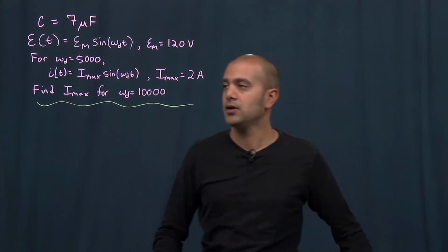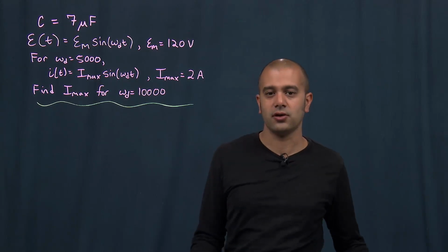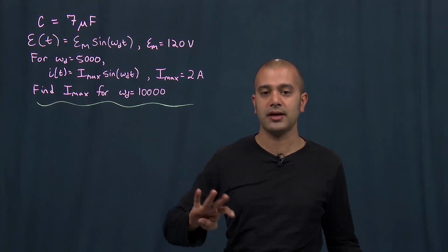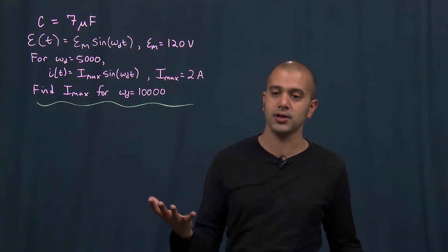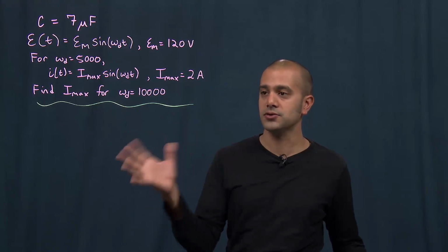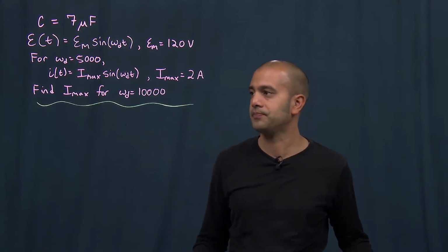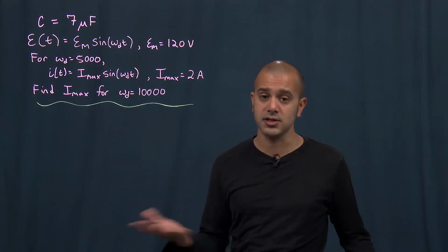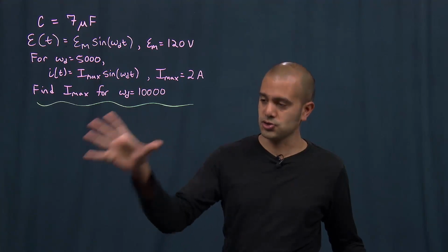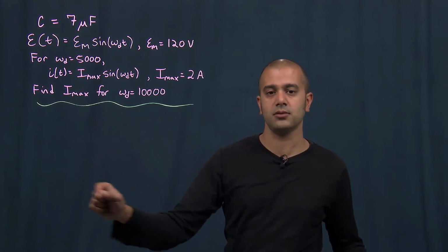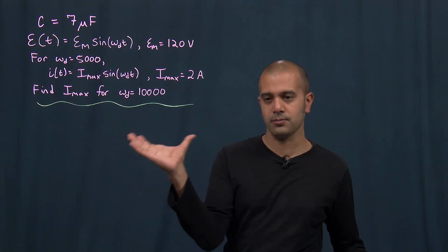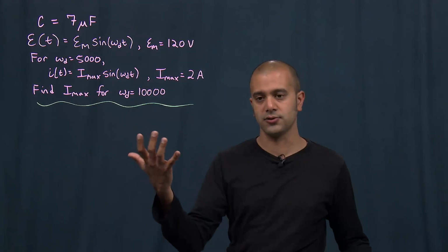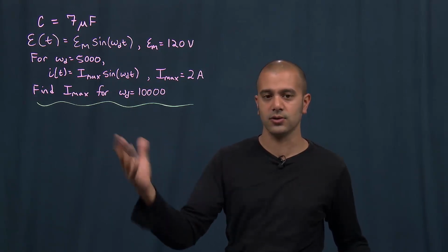So let's start by recalling a few facts about driven RLC circuits. These circuits have one resistor, one inductor, one capacitor, and typically they have a driving source which is oscillatory. Oscillatory driving forces give nice behavior that's very useful for things like radios. The way you would analyze such a circuit is similar to how you would analyze an LC circuit. You draw the circuit, write down Kirchhoff's loop rule by looking at all the voltages, and that equation will give you a differential equation for the charge, which you can solve using differential equations, or you can just guess the form and see if it works out.